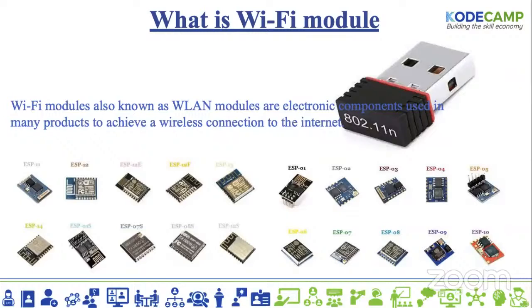There are some of them you can really use for an analog device. For example, if you want to read a physical quantity like temperature, there are some of these devices that are not really good at that. I think there is one I didn't include here, the ESP NodeMCU. That one has just one analog input, the A0. So you can only include one analog signal, because you only have one pin for analog signals. With that, you know which microcontroller is the best for you.